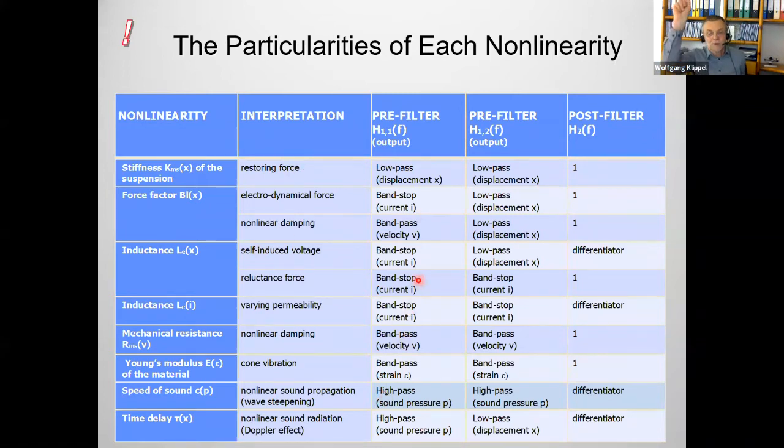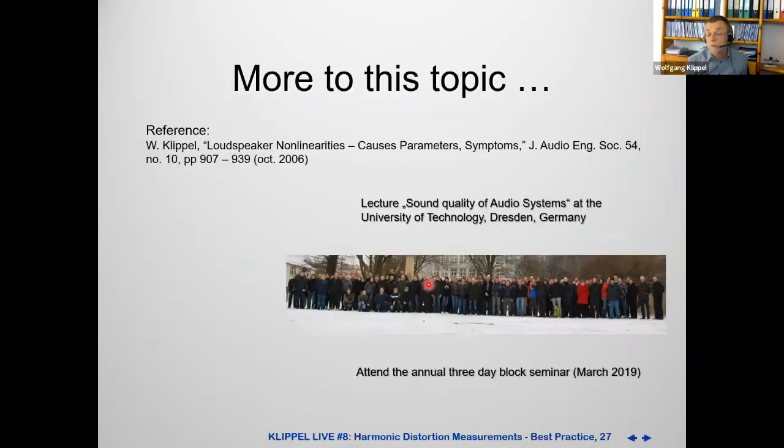Now the interesting point. The filter responses from the two filters generate the frequency dependency of your harmonic distortion measurement. That's why this table is quite important for you to interpret or to explain the last slide where I said the BL is dominant at lower frequencies, something like that. We have not the time for going into this relationship and speaking more about that.